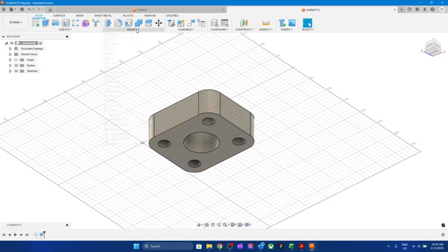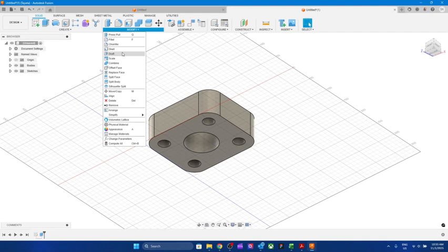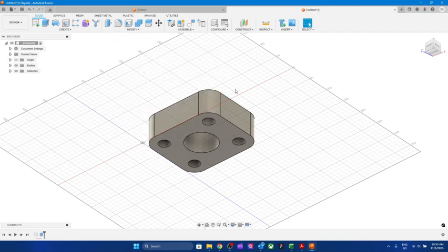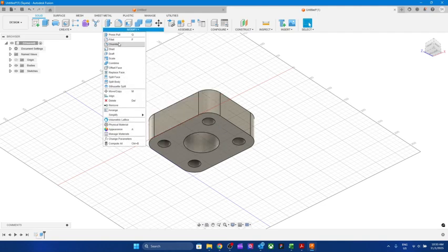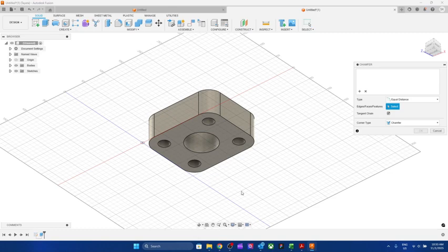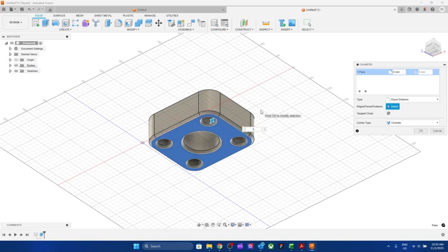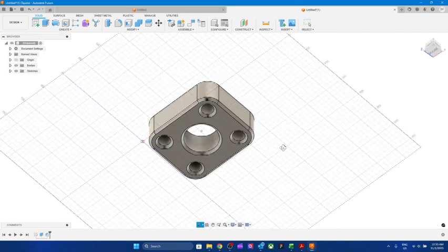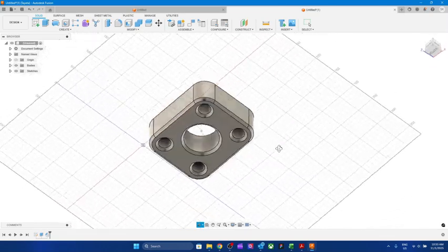If I want more functions here, look, fillet, chamfer and so on. We've put a fillet once, so let's create a chamfer. So select chamfer and I want to select the whole of the bottom face and I want the chamfer to be 5 millimeter. See, immediately it gives a 5 millimeter chamfer and press enter and you've got a chamfer there, 5 millimeter chamfer.